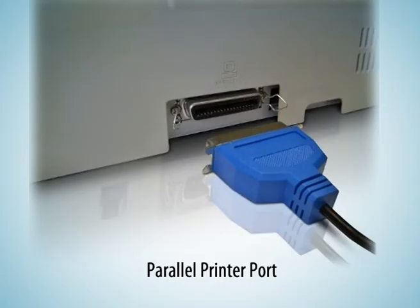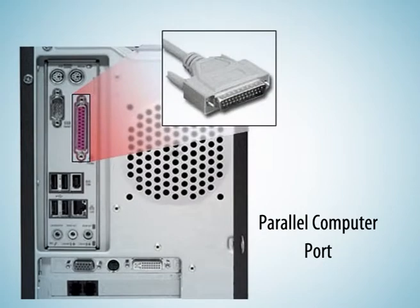The interface typically includes a somewhat cumbersome cable and a 36-pin male and female connector at the printer or other device. The other end of the cable plugs into a 25-pin parallel port on the computer. Data flows in one direction only, from the computer to the printer or other device. In addition to 8 parallel data lines, other lines are used to read printer status information and to send control signals.